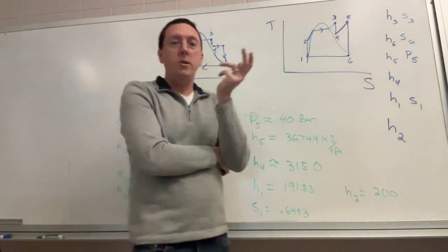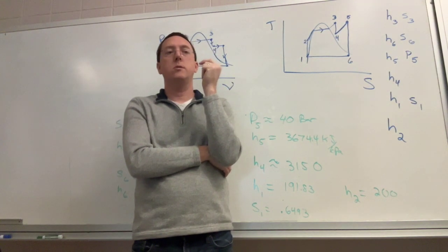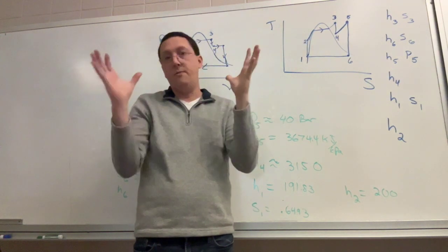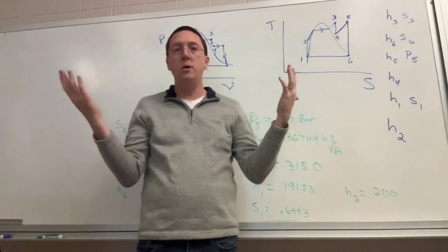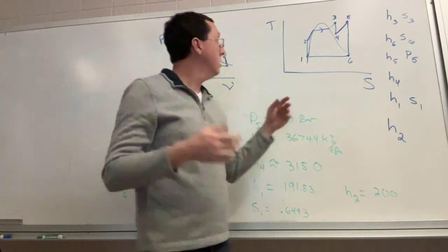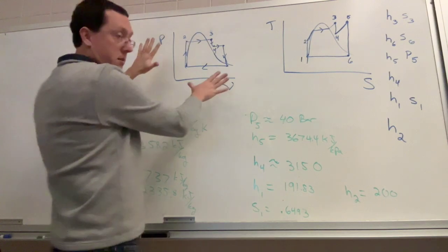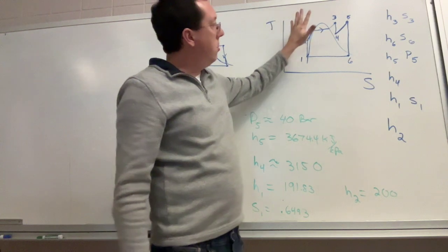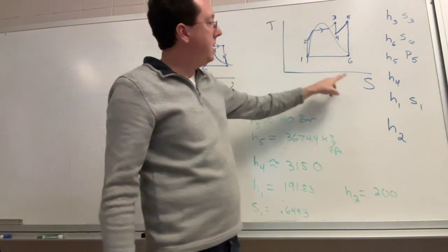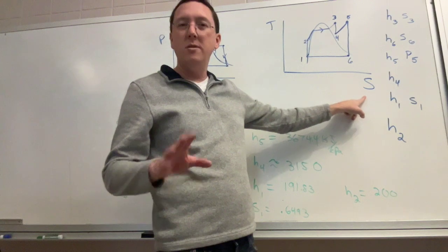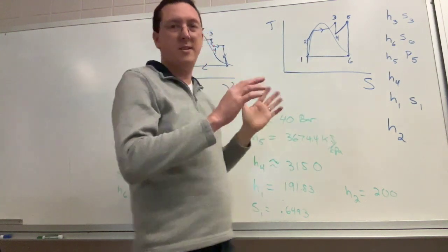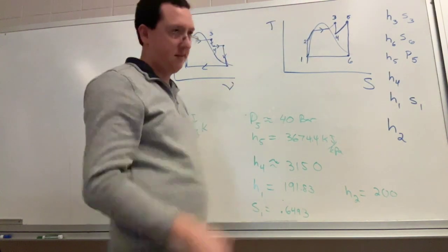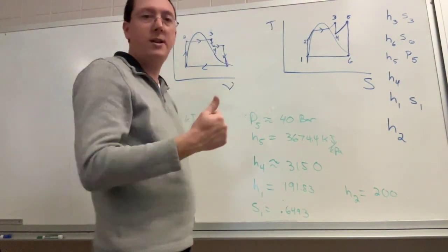So the first thing you need to do to solve any of these is to construct the cycle in the phase diagram. And there are two graphs that we usually use. The first one we've done a lot of, which is PV. The area inside would give the work. Another graph is TS, which is very similar to PV. So sometimes when I talk through it, I'm going to use that as a basis to make an analogy with the PV diagram we already saw.